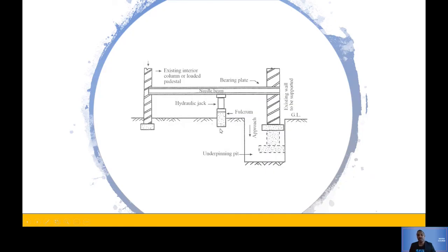So what you do then is what we call underpinning, meaning you are going to extend your foundation. So you need a jack, just to hold the current foundation up. And as you can see what's happening here, it holds the current foundation up. After you are done digging, you can now put your foundation under there. Okay.